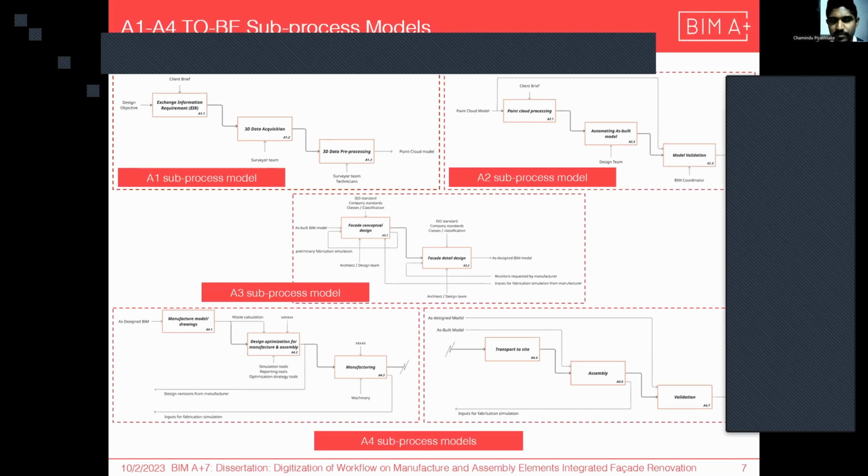the generated BIM model. And in the design stage, which is the A3 sub-process, we can have the preliminary fabrication simulation within the conceptual design stage of the facade, and where if they require any revisions later on from the manufacturing assembly stage, it will be easily done in the facade detailed design stage. And all the feedback from the manufacturing assembly stage should be passed through to the process stages above also.